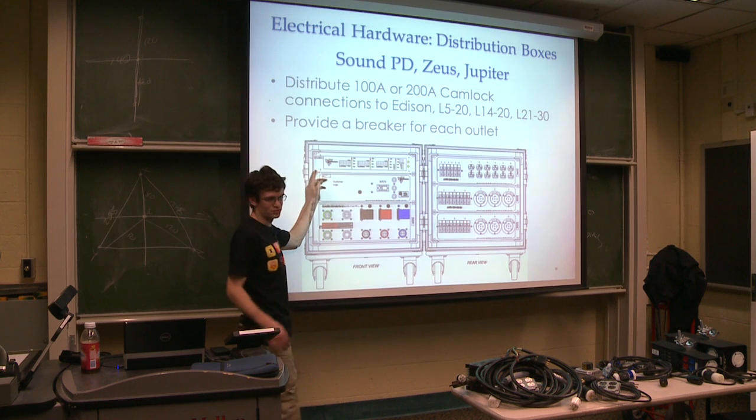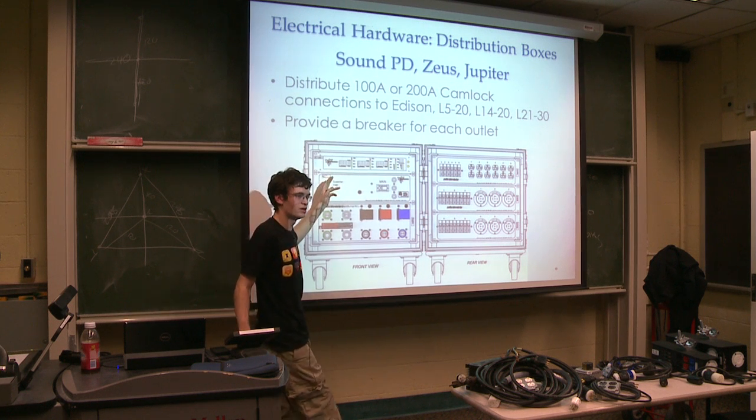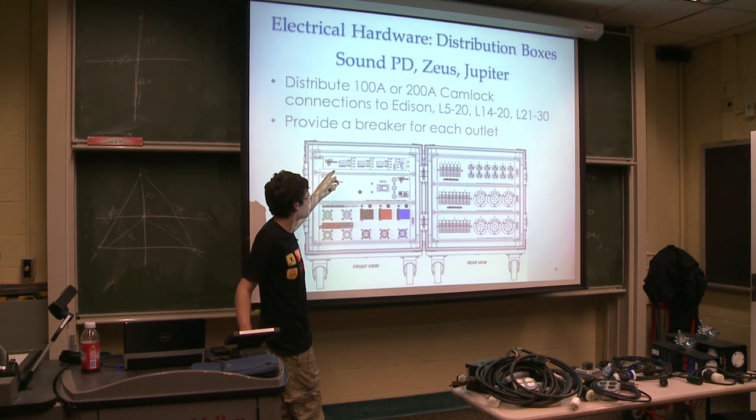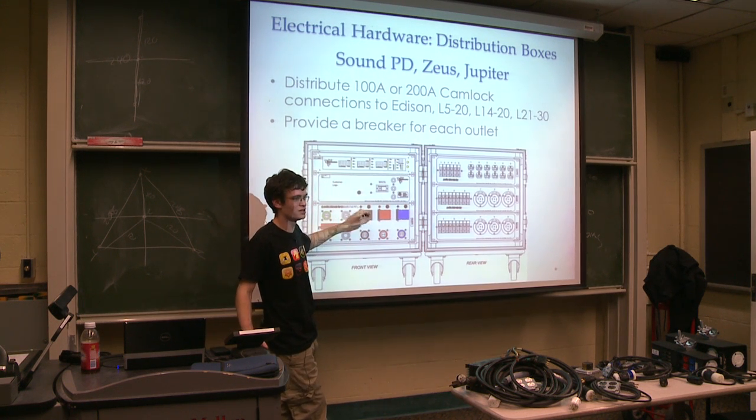They also have meters, which apparently on all of them are slightly off, and they're recording less than the actual voltage, especially for 208 volt. So we might want to actually get those replaced. But they can also give you a rough estimate of the current flowing in through each phase. It doesn't measure the sum of coming in and then going out again.